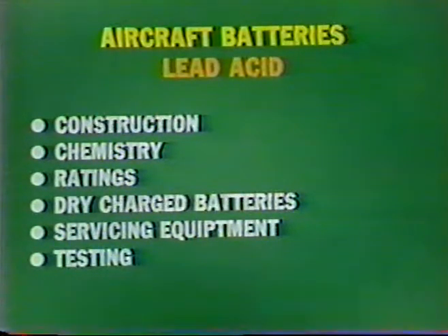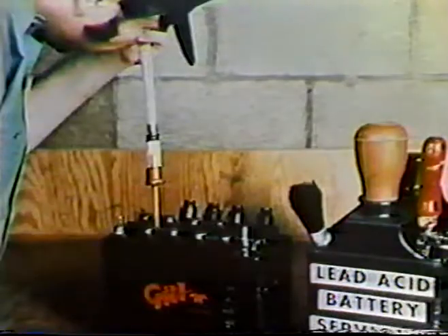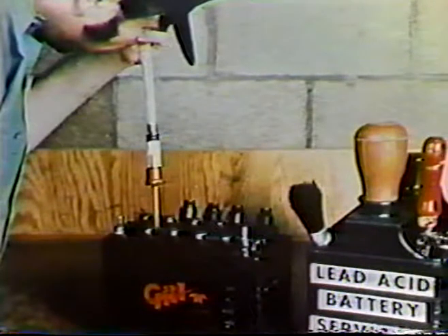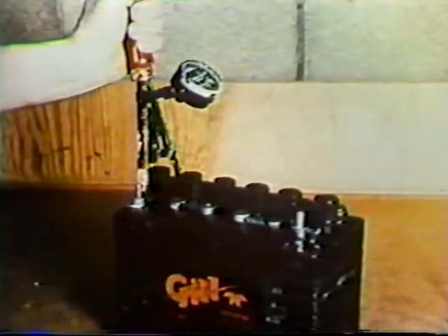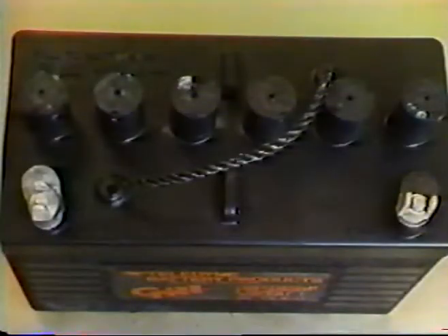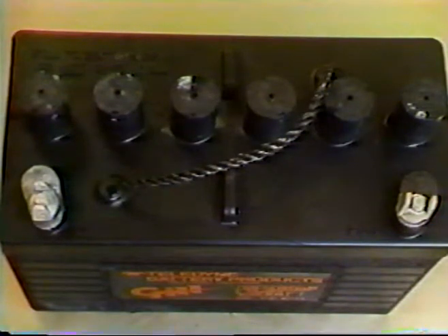Battery testing. The specific gravity of the electrolyte is a measure of the general condition of a battery's charge. Using a battery cell condition tester on each cell will indicate the condition of individual cells. Note, with newer style batteries having internal cell connectors, individual cell voltage cannot be measured. So, check the electrolyte level of each cell and add pure water as required.